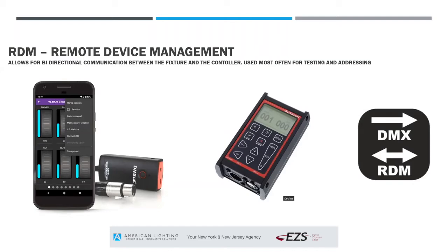Lots of different ways for monitoring are being incorporated with RDM now, because it's allowing DMX, which traditionally is single-way communication, to have two-way communication, and for control systems that are getting more and more advanced and complex to be able to monitor the fixtures themselves and the system. So you may have a fixture that goes offline. You potentially can get an email alert as a building manager, engineer, or owner saying, oh, I've got a fixture that's offline.